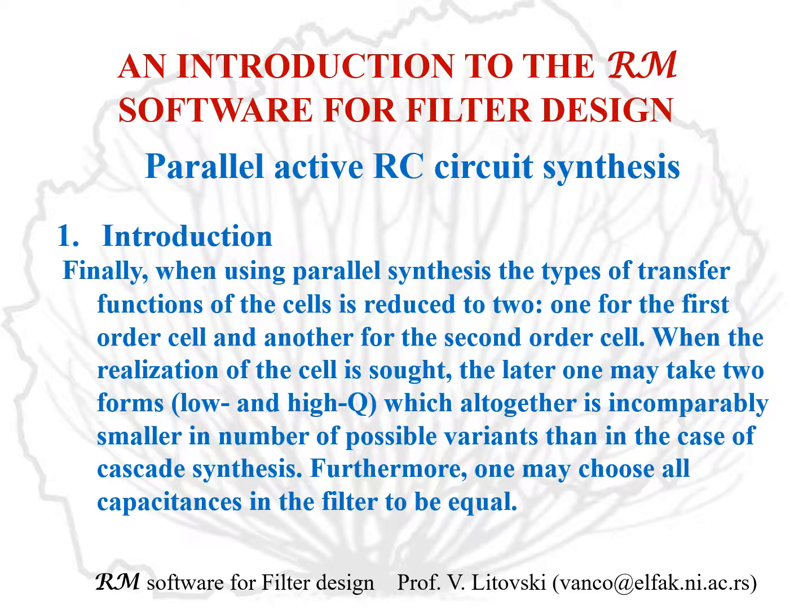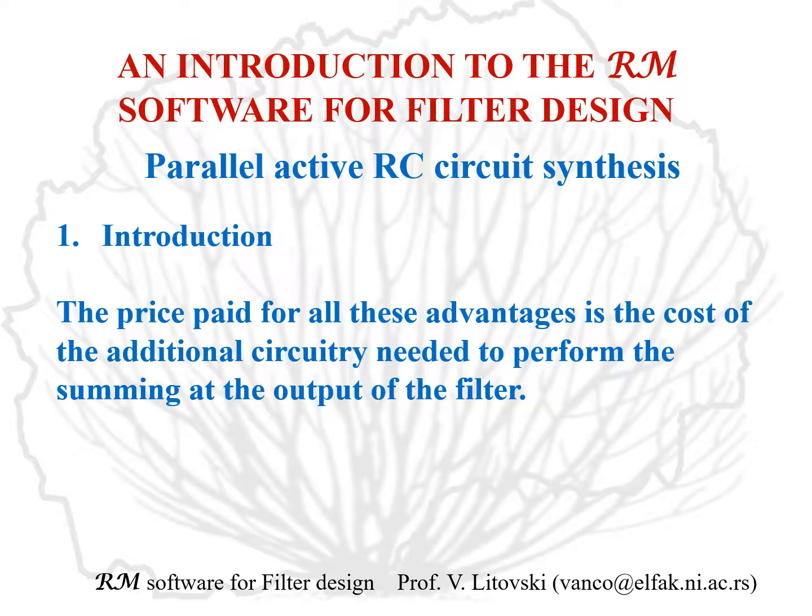Furthermore, one may choose all capacitances in the filter to be equal, which is a unique advantage. The price paid for all these advantages is the cost of the additional circuitry needed to perform the summing at the output of the filter.